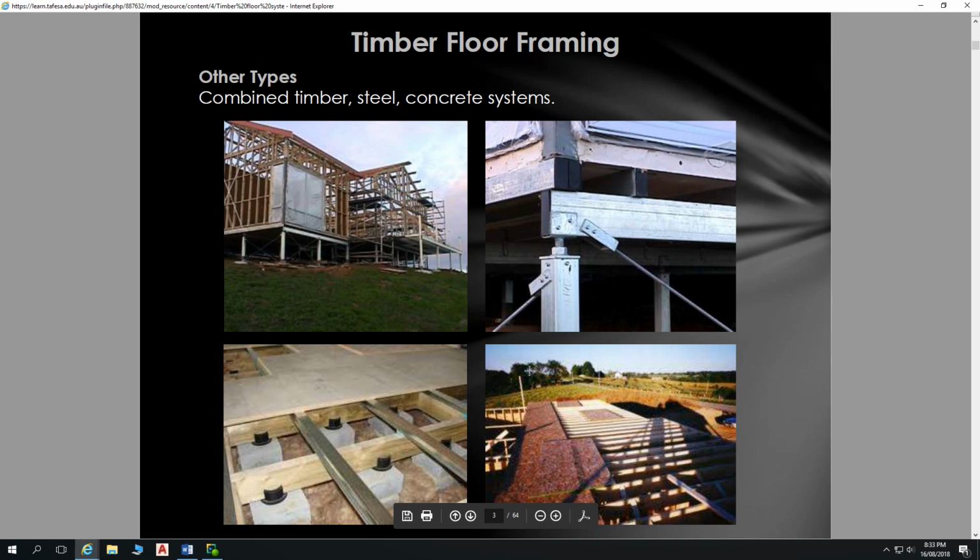With your suspended floors, one downside of those suspended floors is you don't have the thermal mass. So if you have sunshine shining on your floors, it's still a fantastic thing in winter, but you're not storing all that heat inside your house like you are with a concrete slab. But typically significantly cheaper to produce.